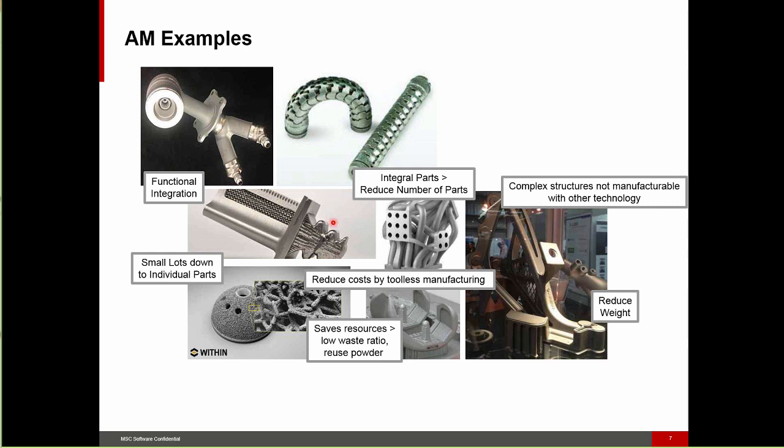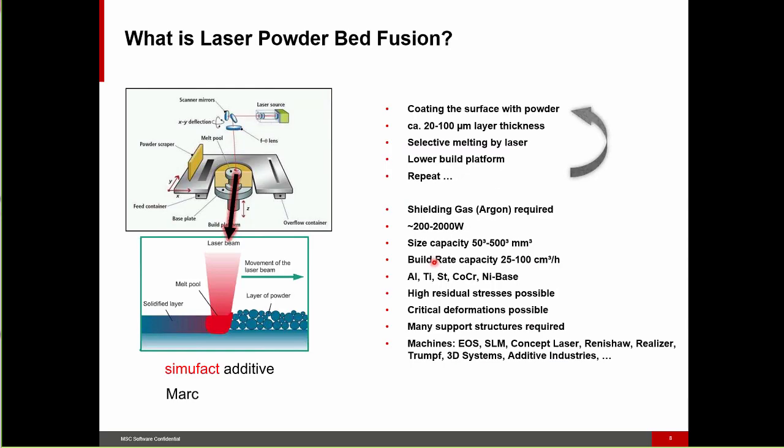Problems of turbine blades are nice to be able to address because we can put cooling passages right into the blades. That use of cooling passages also makes this very appropriate for constructing dies. And one can see that you can really form very intricate geometries, which before you would have done through bending different pipe sections and then, of course, welding or brazing them together. Lots of innovative designs are coming in through additive manufacturing.